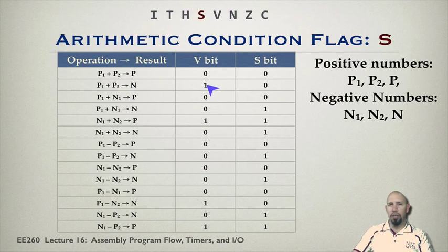That bit told you something goofy was up, but I should have gotten a positive number. So the S bit tells me I should have gotten a positive number. See that? Here, I add these two together, I got a negative number. That gives me negative. Here I have two negative numbers, and there's something goofy that gives a positive, but I should have gotten a negative, right? Here I got a negative, I should have gotten a negative. Here I got a negative, I should have gotten a negative. So there's nothing goofy with that negative.